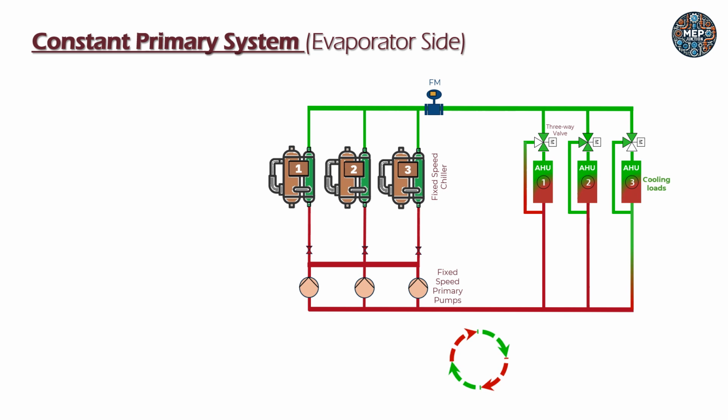These pumps are designed to take care of the head loss across the pipelines, the various valves and the fittings, and the pressure loss across the chiller evaporator coil and the AHU cooling coil. The required flow data is to be provided by the chiller manufacturer for designing of these pumps, or you may consider 2 to 2.5 US GPM per ton of cooling capacity as a thumb rule to get the evaporator water flow.